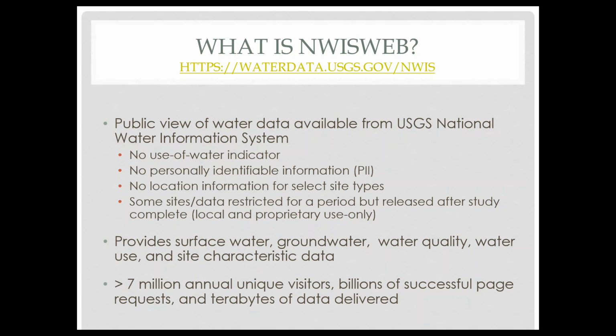One of the things that we will often do if we want to use an existing well, because it's expensive to drill wells in an area to do your assessment or to do your study, is we'll take a borehole camera and we may go down that well if we don't have a well log, if we can't find the folks who constructed the well who tell us that the well is open to the right part of the aquifer, the well is constructed well, and meets those criteria.